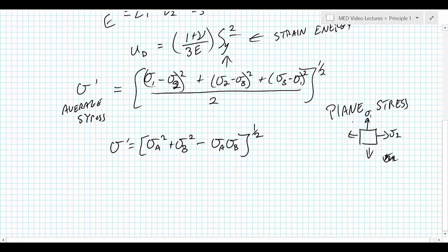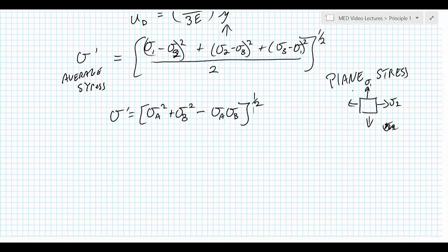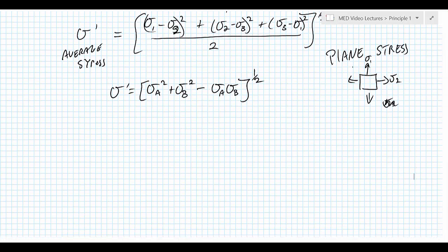Where those are values for principal stresses. Now we could come back in here, and we know how to find principal stresses, say from Mohr's circle, for example. And we remember that equation, and it has square roots in it. And we can come back in here and solve for what those principal stresses are, and simply swap out our sigma A's, sigma B's, with the equations for how we get there. So how we get there is actually pretty straightforward.